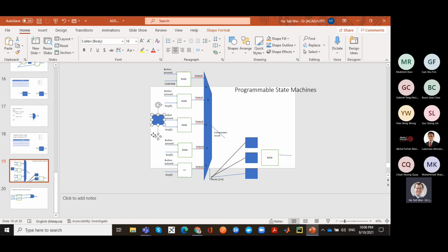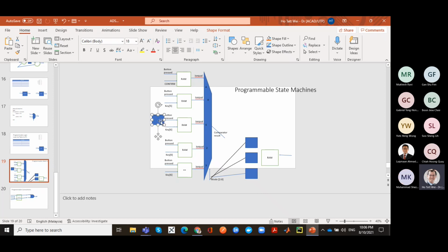I have the flexibility to reconfigure inputs from one versus input for another, because I can reconfigure the calculation, but I can also reconfigure what are the input signals that I'm performing the calculation on. So in the lookup table paradigm, the inputs can be flexibly allocated just by allowing you to load it into memory.